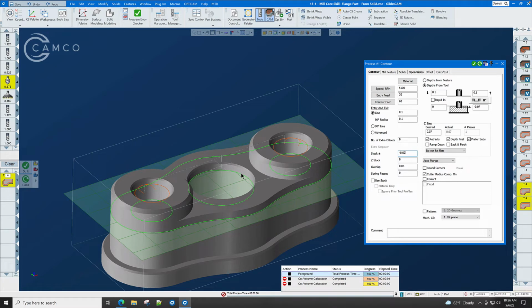And remember, when we're doing chamfers, make sure that the profiler is on the full diameter and not in the chamfer. We set the top of the tool path at minus 250. Double click here, press your Alt key, minus 250. And then we're going to drive the minus 250 down another 70 thousandths. Minus 0.25, minus 0.07 equals minus 0.32. Click anywhere on the circle that bounds the inside of that 1-inch hole and click Do It. We have a tool path.